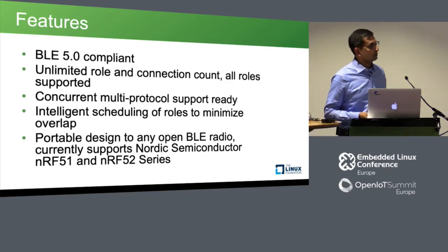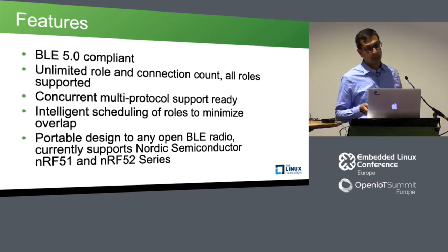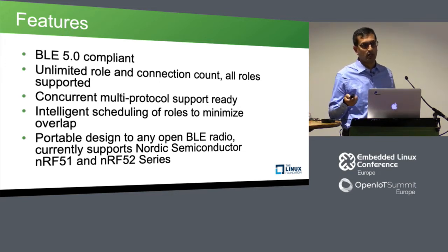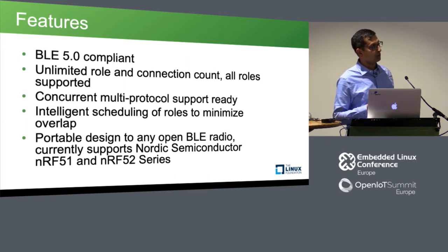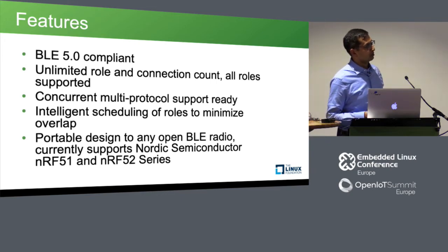What it has is it's fully BLE 5.0 compliant. It has unlimited roles and connection count. What that means is that, RAM permitting, you can actually, I think we have set an upper limit of like 64 as a count in the Kconfig. But you could go more than that also if you want, and it's only restricted by the RAM. It also supports concurrent multi-protocol, and it has intelligent scheduling of roles.